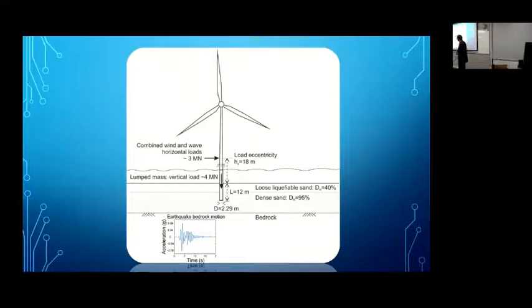Is the big issue. Not only standing up, the people who make these turbines are quite demanding mechanical engineers. So they insist that the rotation at the seabed level should not be more than half a degree. They have good reason to say this, because if I allow half a degree of rotation of this pole here, the movement at the top, which is about 100 meters above in the air, is going to be huge, isn't it? If I rotate something by half a degree here, and I have a very long pole, the amount of distance that has to go is going to be huge.